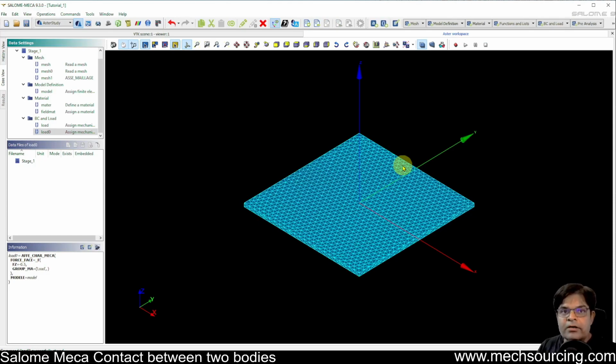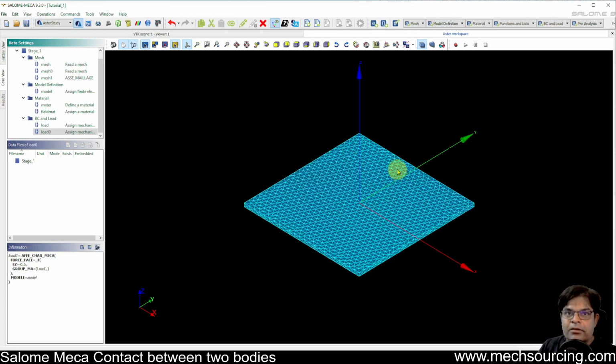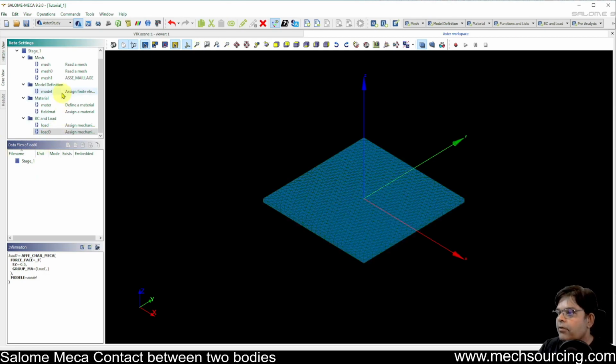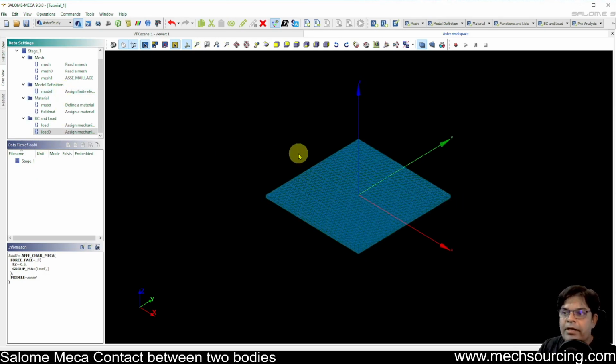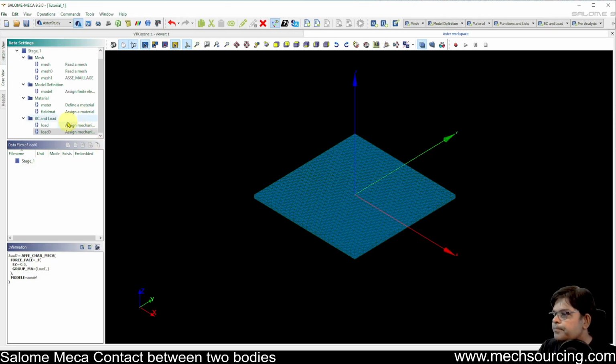So now two loads are defined already, but I hope you remember that we need to model the contact also. I noticed one thing, that there were no contact elements for the frame when I opened that dialog box. Let's see if it is there or not in the meshing model. Anyways, as per my last video, I told you that we also need to create the volume elements for one of the meshes. Why we need it, I'll explain in this video.